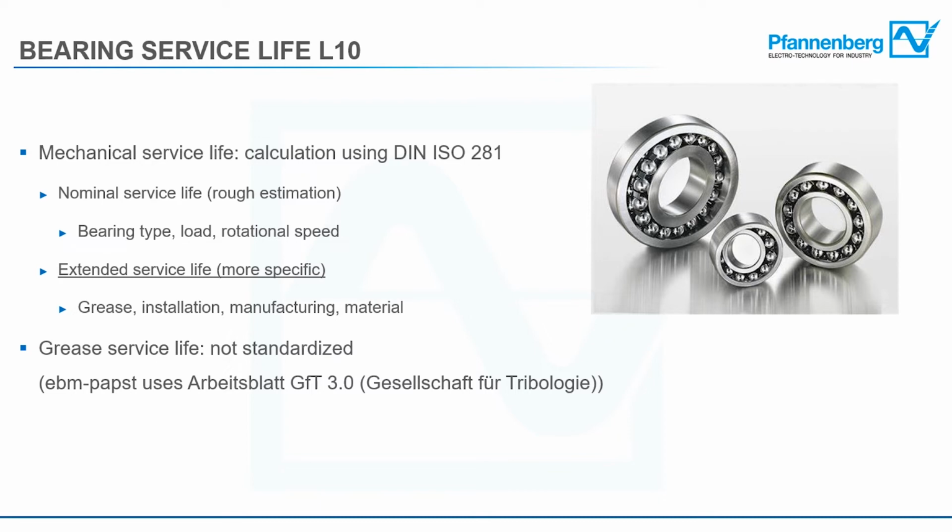For the grease service life, there is no standard as such. However, EBM Papst uses a paper published by the Association for Tribology. In case you were wondering, tribology is the science of interacting surfaces in relative motion. So this association provides a sound basis for the calculation of the grease service life.